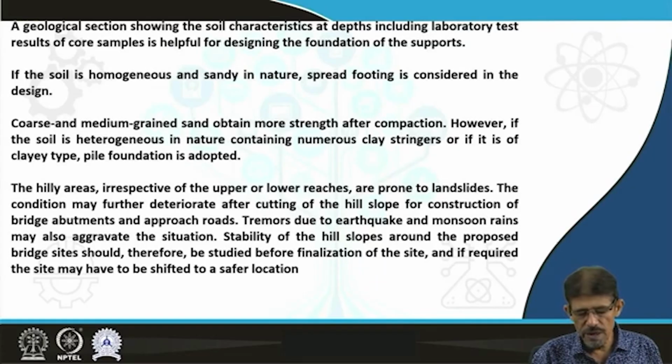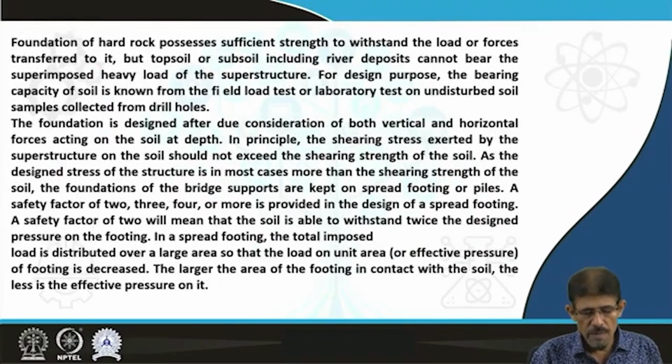Then the geological sections and the soil characteristics we can evaluate by making soil sections, by drilling and collection of samples, etc. Then about the foundation on hard rock, a foundation on hard rock presents minimum problems, related only to evaluation of the strength of the rock as well as the quality of the rock strata as good, excellent or extremely good, etc. Then about the hydrological condition and availability of water regarding the saturation.